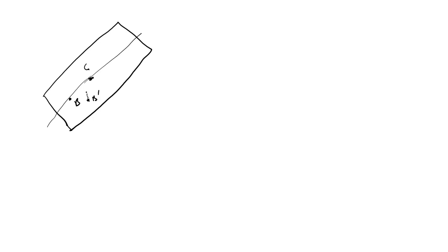So if I draw a vertical line, M will be here, right? So what will now be the direction of this moment? It will be clockwise. So it will move this block away from its neutral position. Hence it is unstable equilibrium, right?